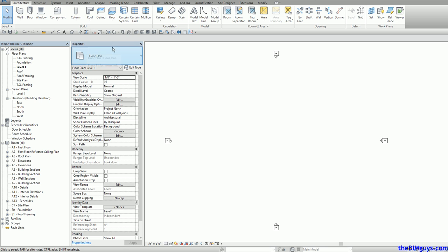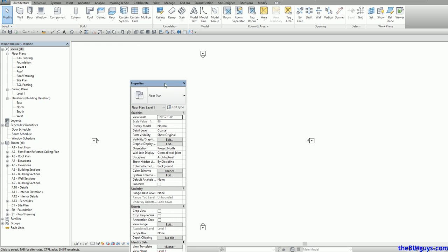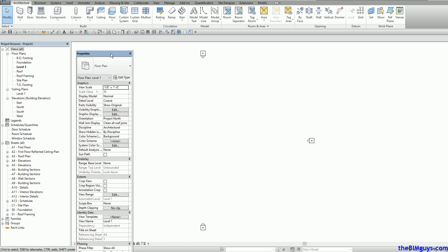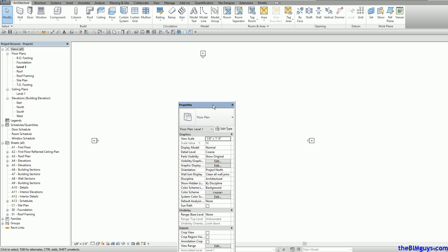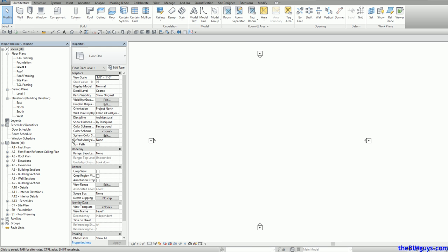Now, when you drag these out, people have a tendency to kind of float them right here, and I don't recommend doing that because, see, it actually is overriding the stuff at the bottom. So what you want to do, this is a little weird, drag it out in the middle. Okay, go ahead and drag that thing right in the middle. Now, where you're going to bring it is, you're going to take that little arrow right there, and you're going to touch it on the center of this bar right here. And that's going to dock it. So you bring it on over, you touch it, and it should at that point dock. Yeah. And once you hit there, you let go, and it should dock it.